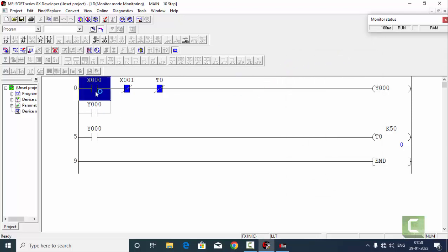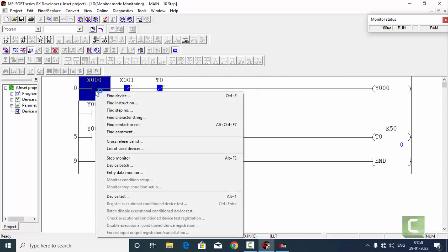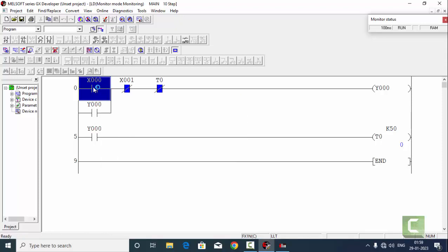Now we just have to click over here. Press shift and enter to trigger the input. Once we trigger it, this contact is closed and the output coil is energized, and this parallel contact with the same address. So when this is energized, this normally open parallel contact is going to be closed, and here we can see it is connected in parallel, and this goes to the Y0.